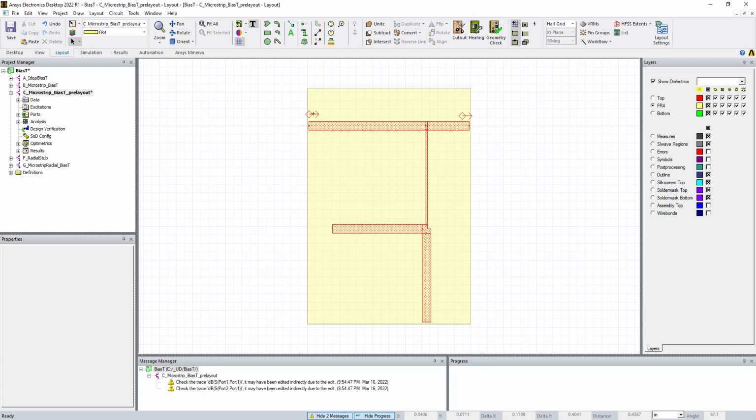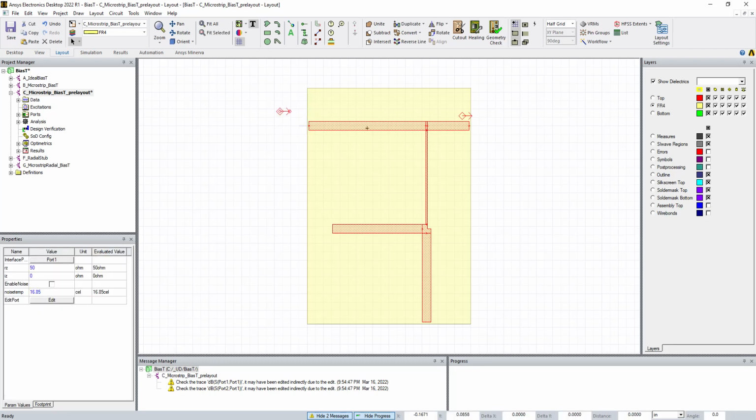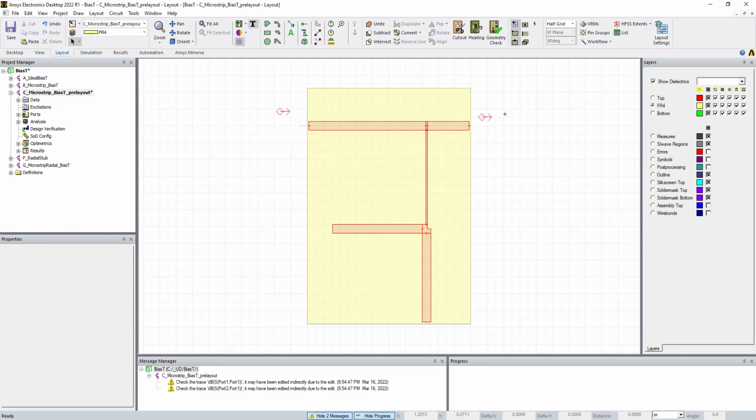And just so you understand, see these little things, these are just the ports. Just move them out of the way. In terms of laying out, they don't have any influence on us. And you'll see why I did this W connector offset in a bit. We're going to have an SMA connector here, an SMA connector here, and we're actually going to put one here as well. Okay, so that defines the dielectric layer.